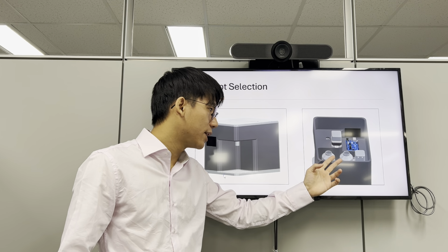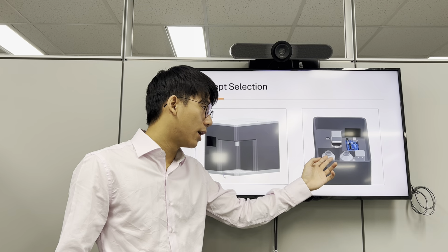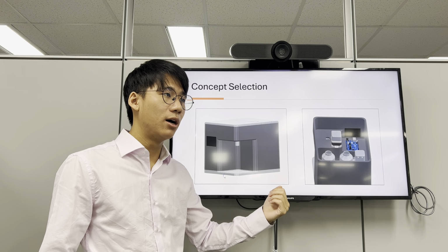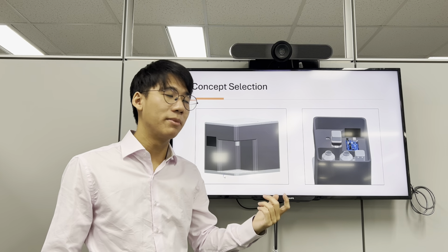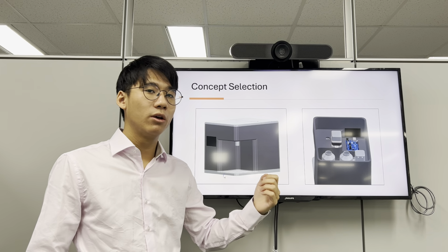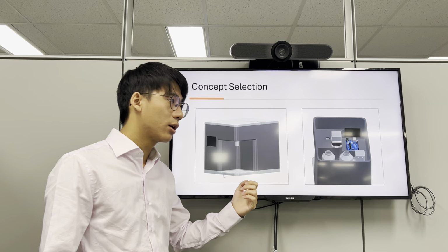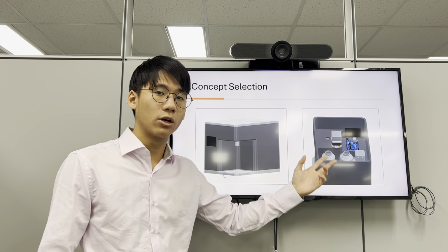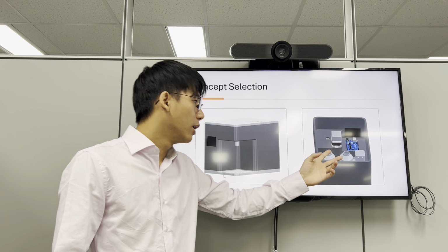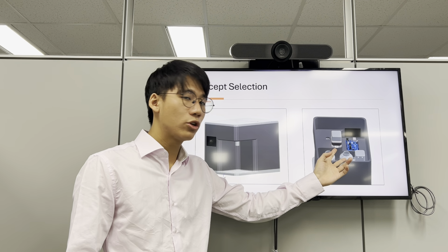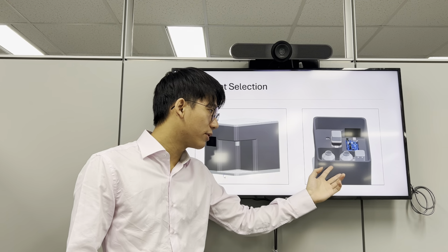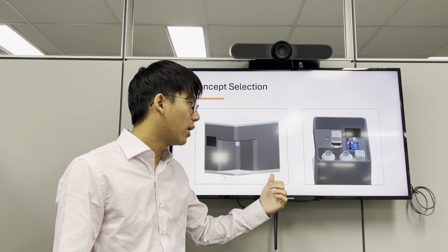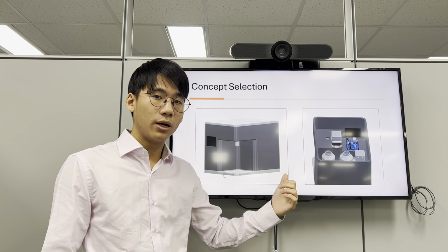We're going to use a standard tank that can hold up to 1 liter, which fulfills our requirement that the machine fill 3 500 milliliter cups without refilling the whole machine and the beverages. We're going to use 4 different tubes into 4 different tanks in order to have better control accuracy of the filling liquid.